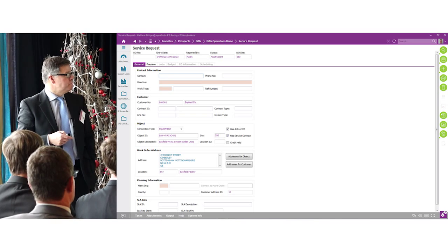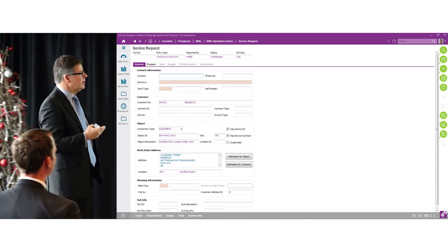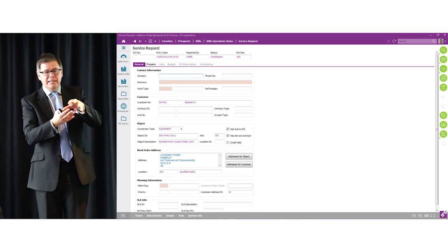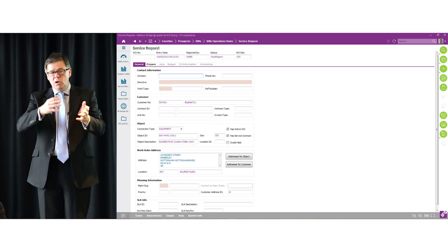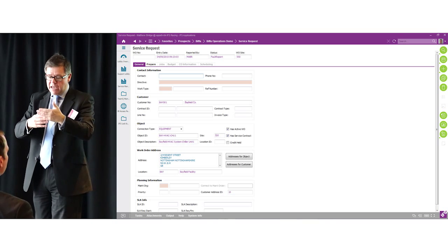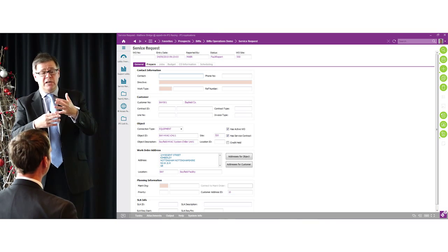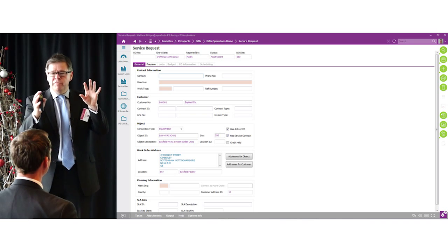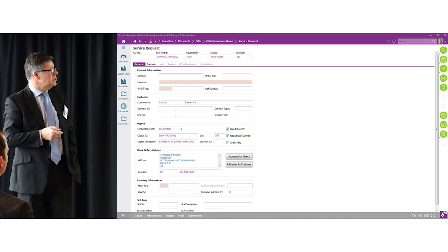The whole area of preventative maintenance is defined such that if we have a task that has a calendar and a condition check, we only do one. If we have a 1,000-hour check and a 5,000-hour check, and the 5,000-hour check includes the 1,000-hour check, then we only do one check. All of that optimization of task management has been done here.